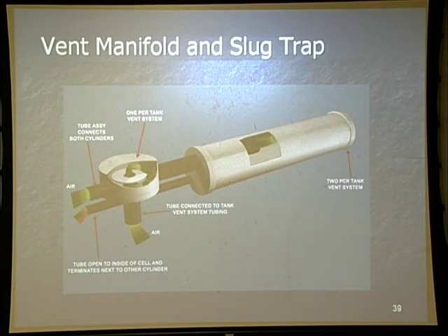Is there going to be a little bit of residual fuel in there if this aircraft were to roll over? Sure. And reality is this is just in case. That fuel's heavier than air, and it will fill the bowl, allowing only air to be vented overboard. Any questions? And as the air passes over, whatever residual fuel is in there just evaporates? Exactly. Anything else?